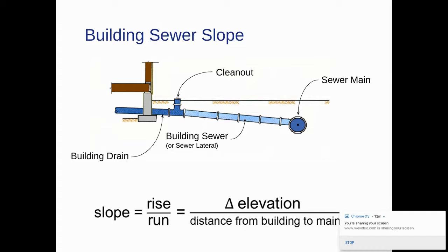The house had sat empty for about a year or so, and inside the house before it reached the main sewer drain, from the kitchen sink, there was a bunch of grease that had solidified. I tried to clean it out myself, popping some of these cleanouts off and putting a little snake down through it. It didn't quite work, so I had to get a plumber to do it. But that's why you have these things, to be able to clean it.